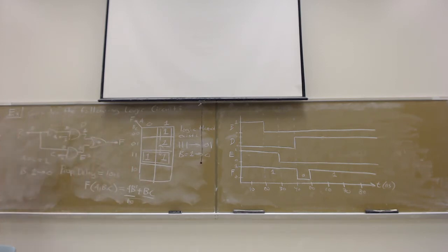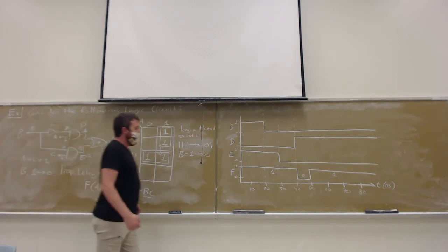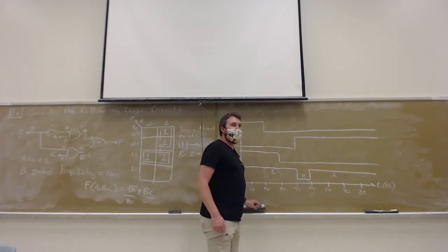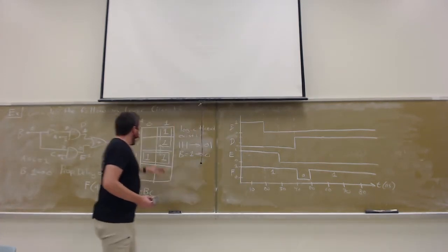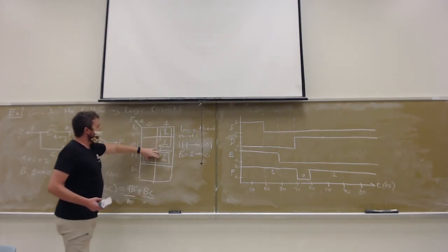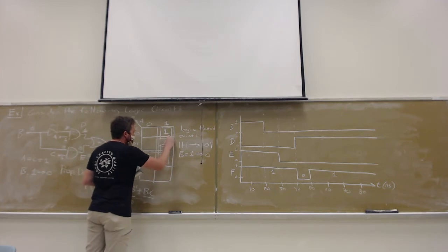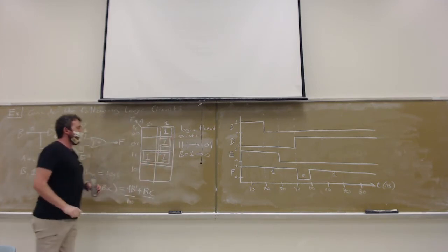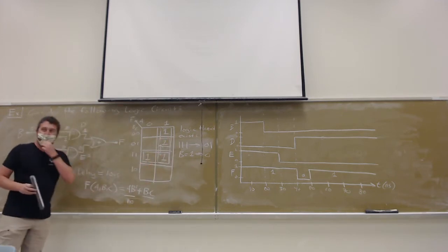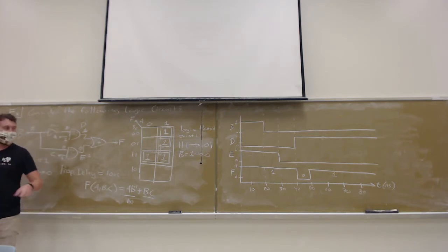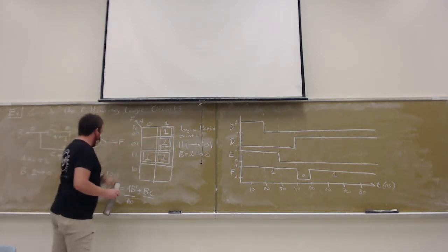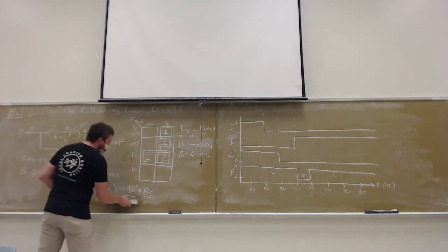Now the way that we get our logic hazards out is by creating those consensus terms. Remember that we talked about if you have terms that are already grouped up, and you make a group that combines two, what you'll get is the consensus term of both of these terms. We can demonstrate that.